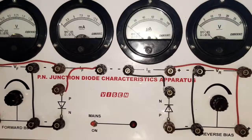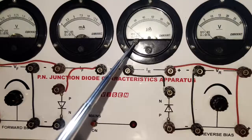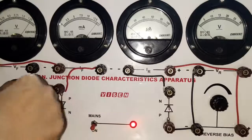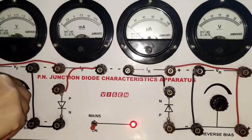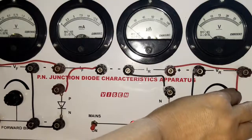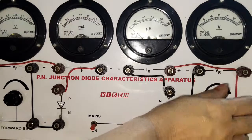Now we move on to reverse bias and study the IV characteristics. We are going to vary the voltmeter and see how the current varies. So we have to put on the power supply, change this knob to minimum, the forward bias we don't need it, and we are at reverse bias, so we are going to use this knob and vary the voltmeter and take the ammeter readings.